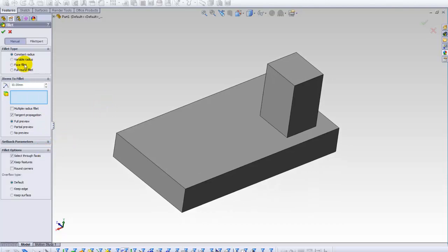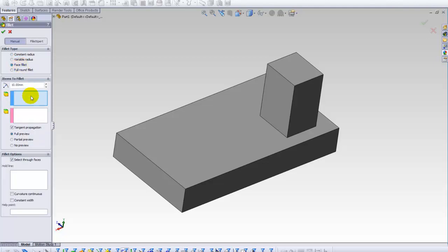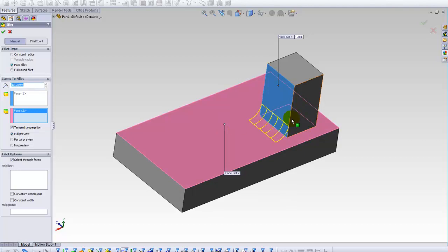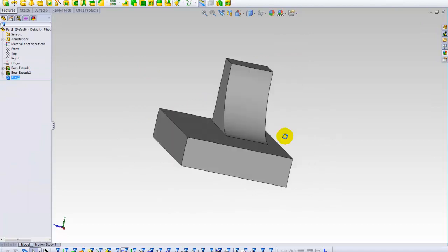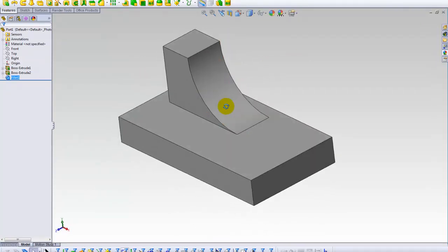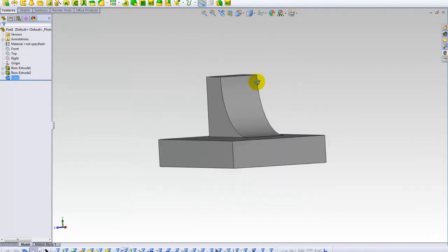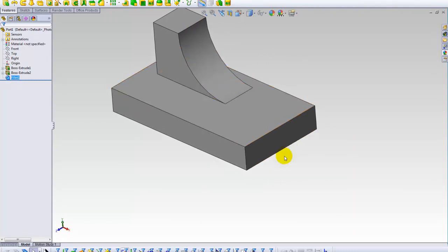So you have to select face fillet first. Okay, first choose the first surface, and for the second face, I choose this. You see a preview here depending on the radius you give, but if you select hold line here, where our line is up here, you don't have the chance to input the radius value, but it automatically arranges it for you, and you have your radius right at the end of this surface. It ends at the edge here. Well, it may look nonsensical in the beginning, but it is pretty useful in specific cases. So I think it's better to keep it in mind.